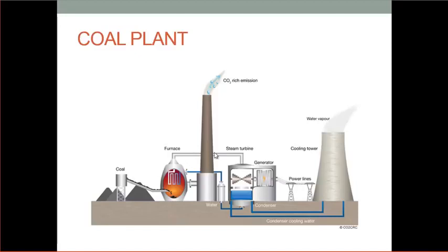So, very simplified version. But here's the thing: this furnace and this turbine take a while to get started. I can't just flip them on and off as I need to, because I've got to burn some coal, and get it hot, and run water through it, and I've got to preheat my turbine, and then get it all hot enough that I'm generating steam. So I can't just start and stop this plant. It might take me 8 or 10 hours to get the plant started from a cold start. And then once it gets running, I want to keep it running.